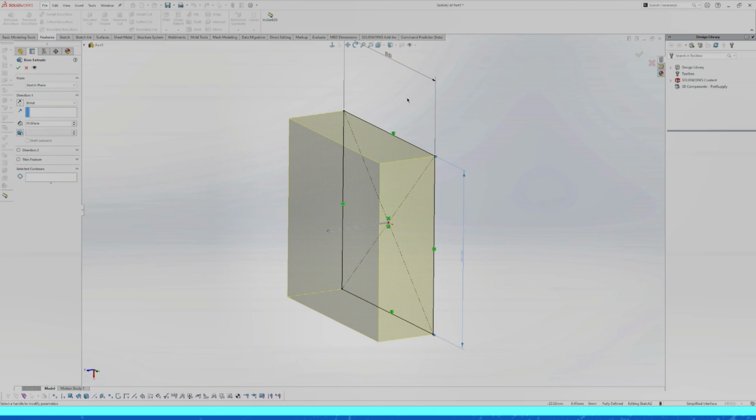So I want it to be a cube. So I'm going to make this be 30 millimeters. So we have a few different options here. We're actually going to do two directions so that our center origin is the exact center of the cube. So we will make this be, we're going to hit the equal sign, 30 divided by 2.